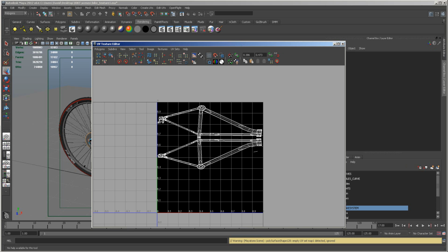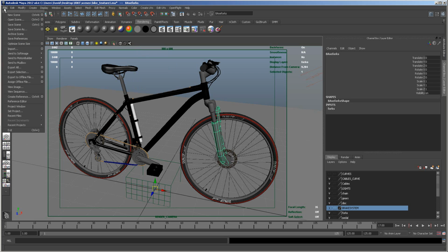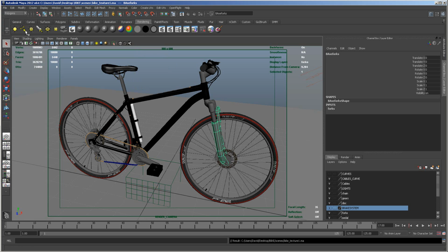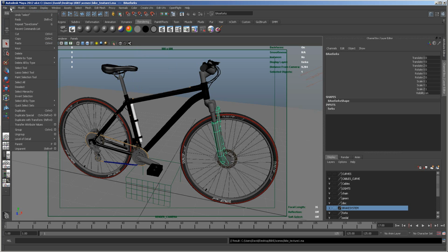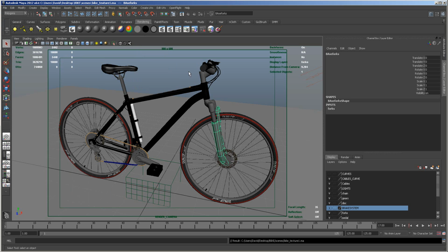And let's just prove that to you now. I'll take this and I'm just going to click it here, and I'm going to do a Z projection for it, but before I do that I'm just going to save it. I'm also going to kill off any history that's in here which could cause the program to crash, so I'm going to delete the history for that.